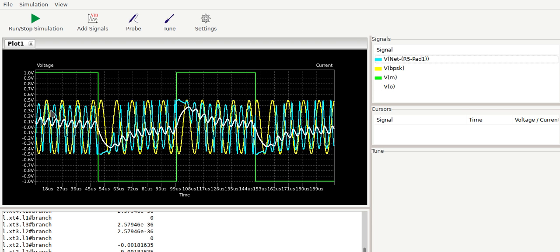If the signal is in phase with the carrier, then they are multiplied together and you will get positive values, and if they are out of phase, you will get large negative values. That's what is happening, and then we are filtering it and collecting the baseband information.